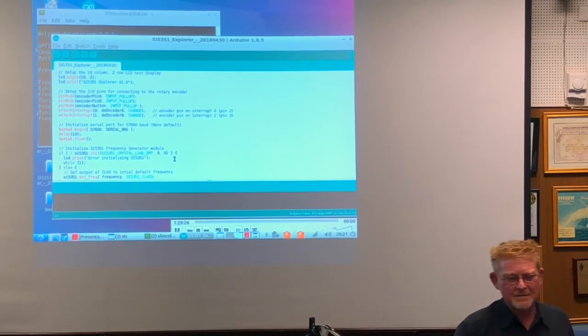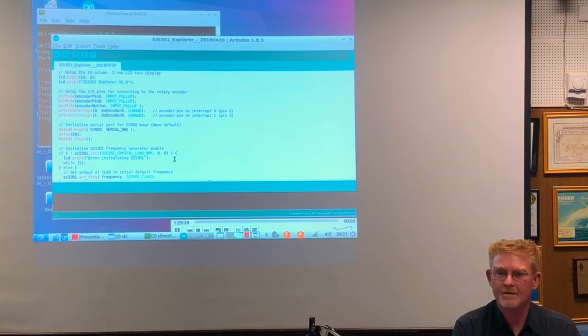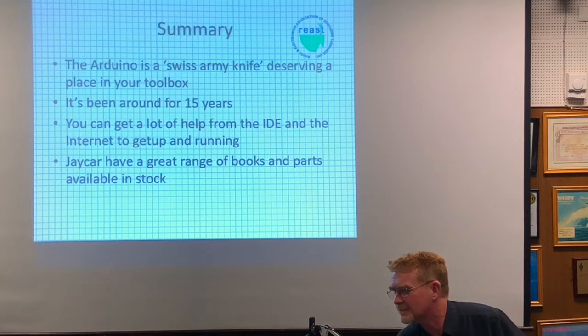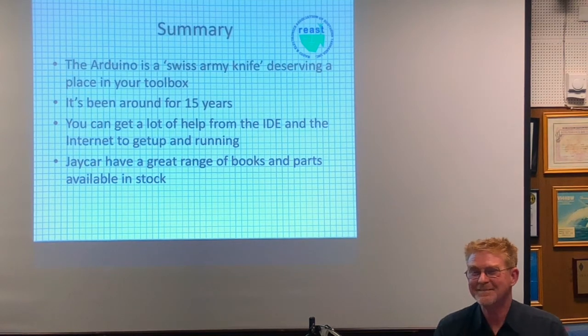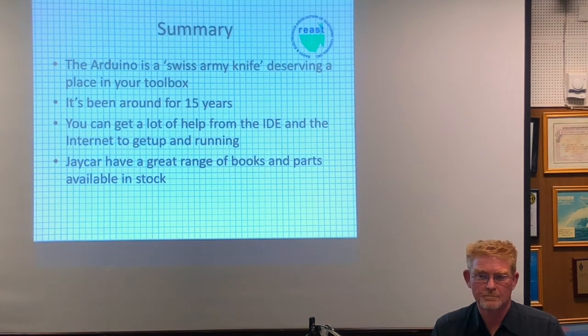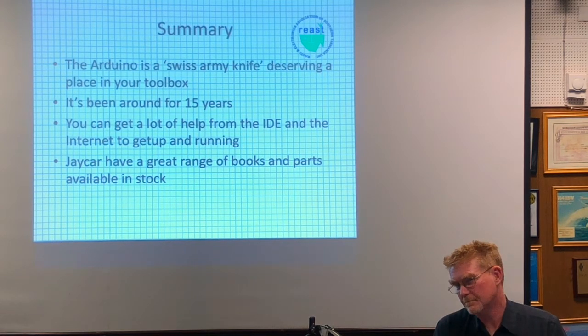Larry: The 5351 has a 25 or 27 megahertz crystal. It's that little silver thing. It's hardly visible. I can't see it, I'll take your word for it. If you're careful, you can strip it off. And the 5351 chip has an XA and an XB input, which is the crystal input. So one is hot, one is ground, essentially. I have not yet done this, but I've stripped off the crystal.